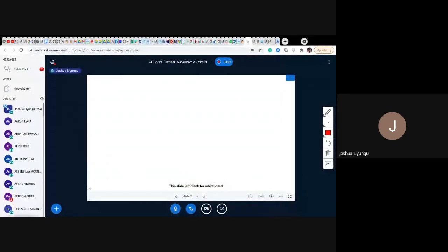We also need to show some supports along the external boundary. The third step is you identify all forces which act on the system that you have isolated.